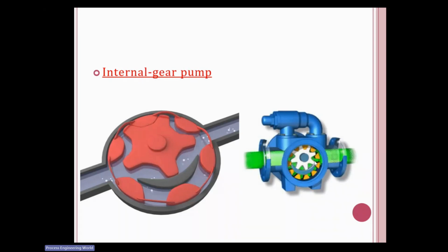If you have a viscosity of more than 10,000 cP, then a centrifugal pump won't work. You have to use AODD pumps. So AODD pumps are used for highly viscous fluids. And if a fluid has high viscosity, then it will have a higher density by default. Okay, sir. Thank you.